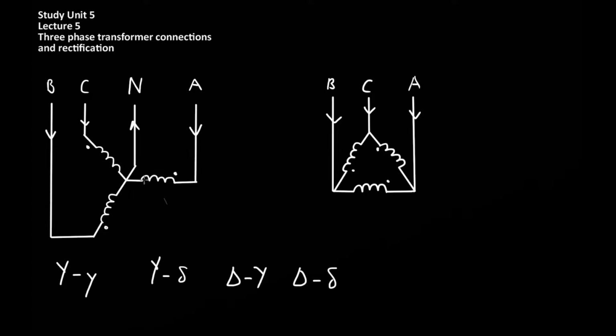A Y configuration will reduce the winding voltage by √3, whereas a delta configuration will reduce the winding current by √3. So for example, a YY configuration might be necessary when two neutrals are required for grounding purposes, although a problem with the YY configuration is that there will be triple-N currents which flow through the neutral and need to be minimized by designing a beefier neutral terminal.